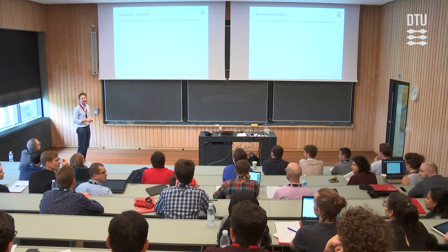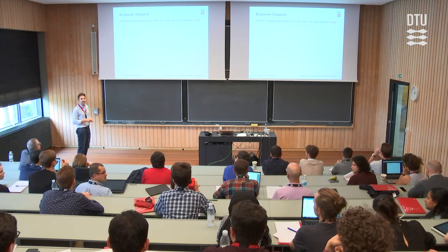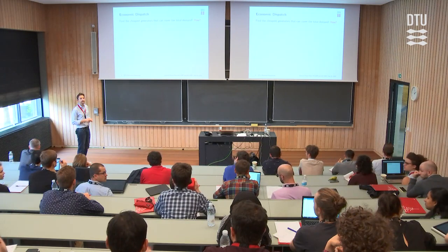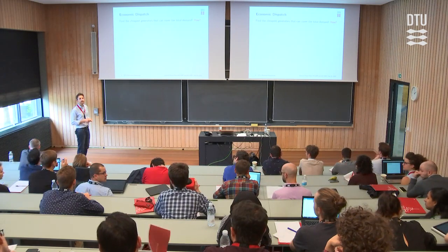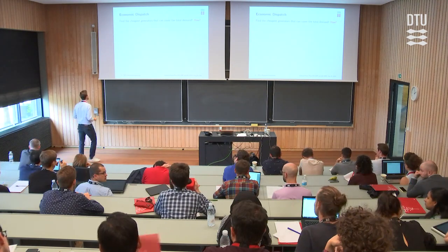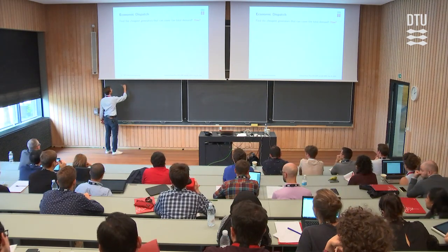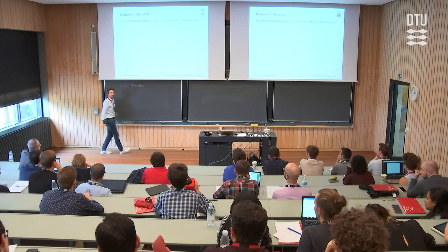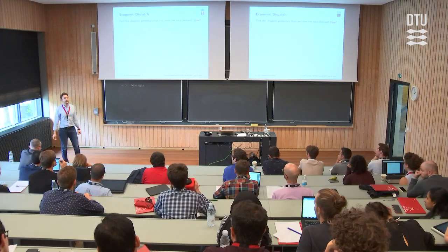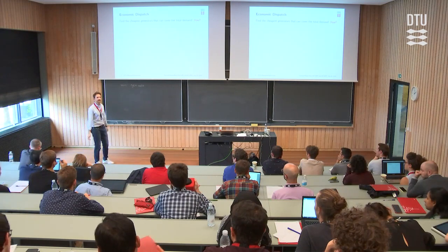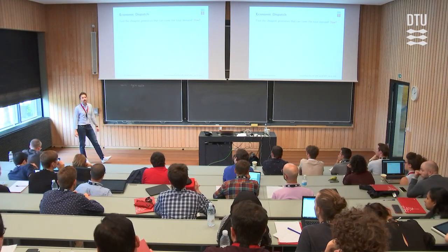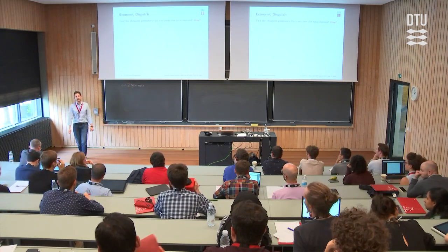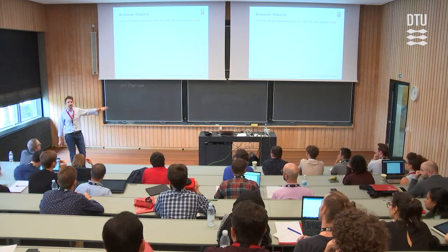Well, our objective is to minimize the generating cost, and then we can first see what the components of this cost are. There may be an operating cost and a cost for starting up or shutting down. So minimize generation costs? Yeah, and so it would be the sum of the generation costs during the individual periods over our planning horizon. Okay, let's suppose that we have one time period. Okay, yeah, so it's the generation cost, then plus possibly the starting cost. But this is more for the unit commitment. I'm just talking economic dispatch.